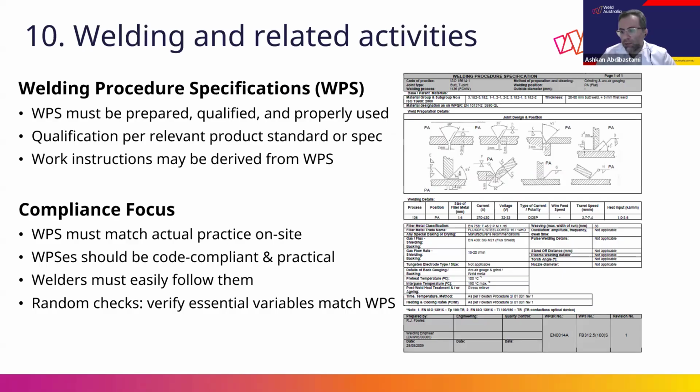Welding procedure specifications, or WPS, must be prepared, qualified, and used correctly according to the product standard. Sometimes work instructions based on qualified procedures are used instead of the WPS directly for welders, because it's easier for some welders to work with. Compliance here means having valid, practical WPS that welders follow and that meet the requirements of the welding standard or code.